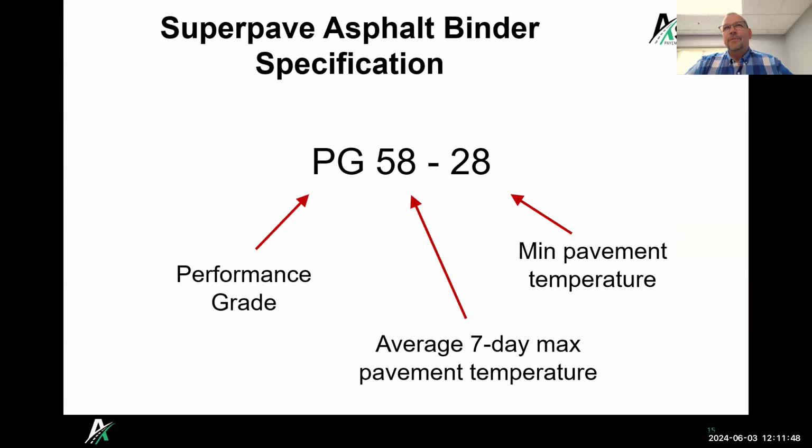Those are all pretty much universal. The EL is unique to Michigan. The original Superpave designations were like E03, E1. There were a whole bunch of them: E10, E30, E50. There were originally 7 different traffic designations. A lot of the states over the years have combined some of those to simplify things. A lot of them went to a low, medium, high volume. Some of them went down to 2. Michigan was one of the last states that was still using all 7 designations.